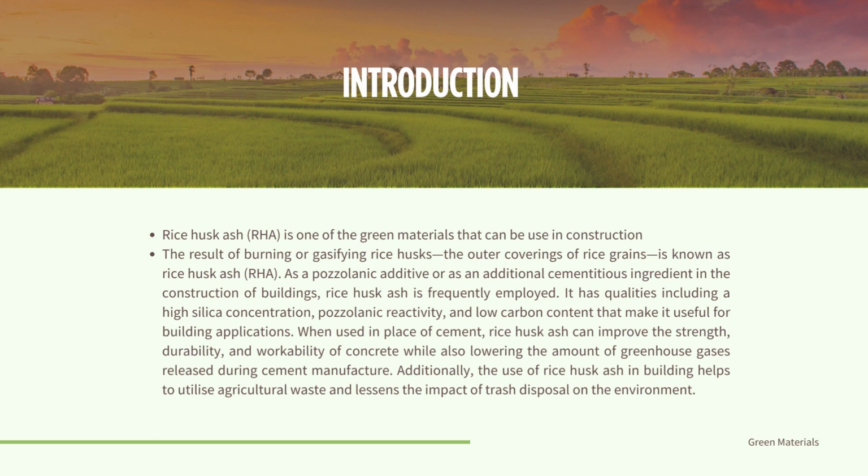It has qualities including a high silica concentration, pozzolanic reactivity, and low carbon content that make it useful for building applications. When used in place of cement, rice husk ash can improve the strength, durability, and workability of concrete while lowering the amount of greenhouse gases released during cement manufacture. Additionally, the use of rice husk ash in building helps to utilize agricultural waste and lessen the impact of trash disposal on the environment.